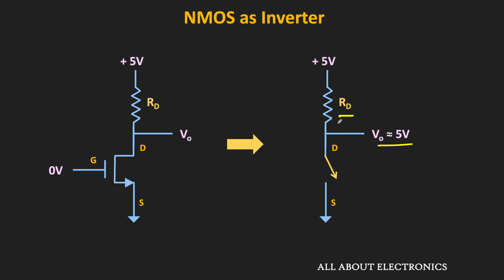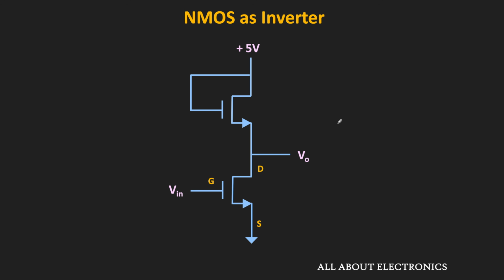So in integrated circuits, instead of a resistor, the MOSFET is used as the active load. As you can see over here, for this MOSFET, the gate and the drain terminals are connected to the VDD. That means this upper NMOS transistor will remain in the on condition, and in the on condition, its on resistance will provide the required drain resistance for the lower NMOS transistor.